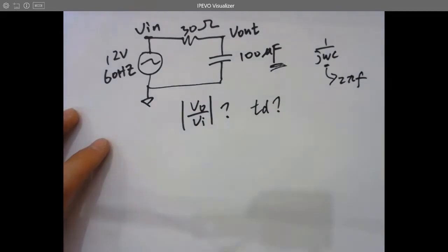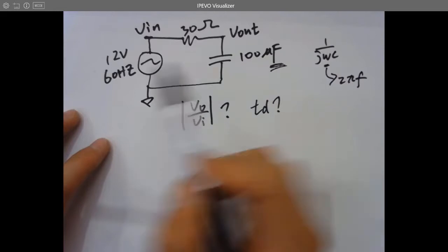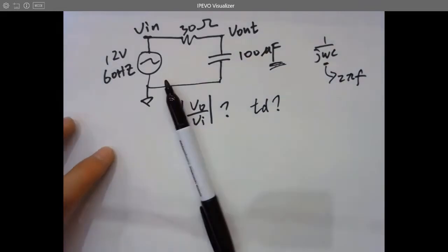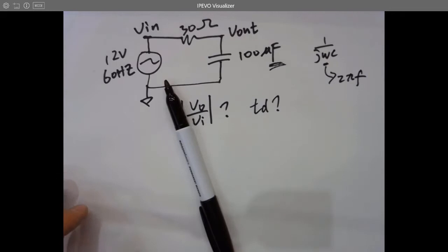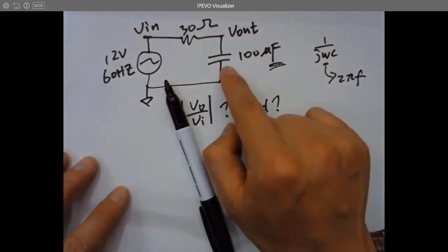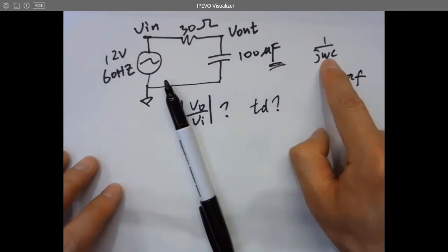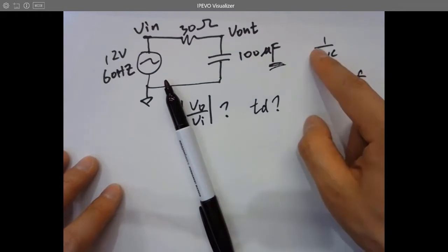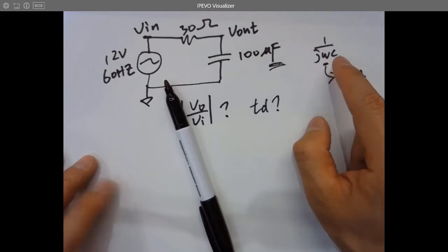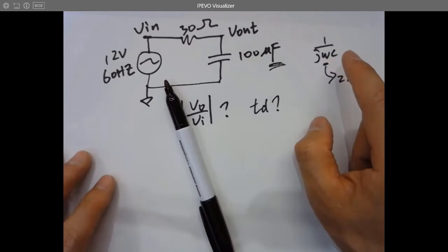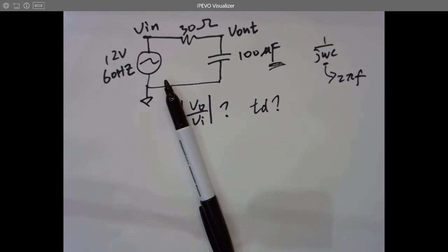So will this guy show you a low impedance with higher frequency or low frequency? I mean, high impedance with low frequency or high frequency? Low frequency, this guy seems like a higher impedance because lower here, higher overall, right? Is that making sense intuitively? Not according to the number, but think about the frequency of the signal. If you inject an AC signal to a capacitor, is it easier to pass with a higher frequency or a lower frequency? Higher frequency is easier to pass. So you can think about it in that way.